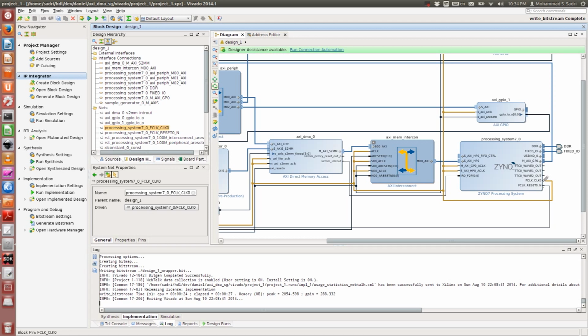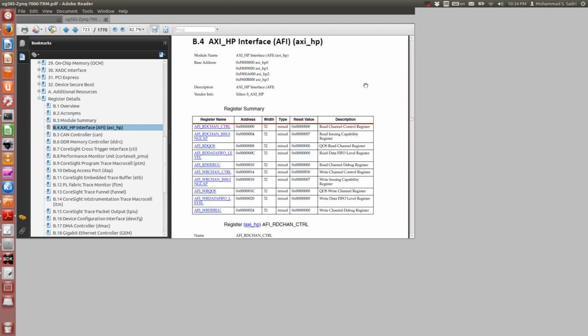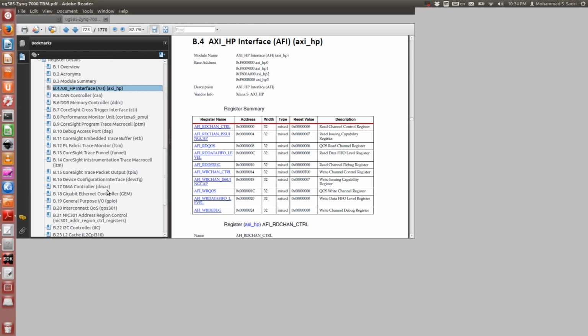So up to one point the clock can operate at, for example, 50 megahertz, and then you can even change it. Or at initialization time you can select a clock frequency other than the default frequency of 50 megahertz. So these parameters are actually very important, and some of them are more important obviously, and during your development you will certainly reach some points where you need to change some of these registers, in fact through your code or manually.